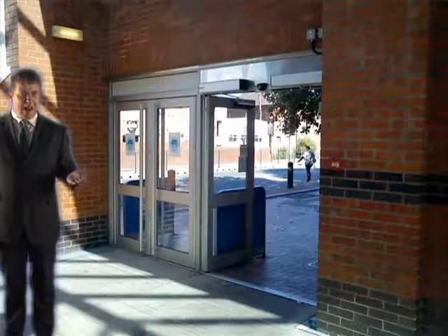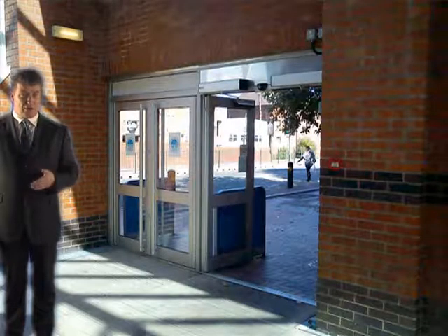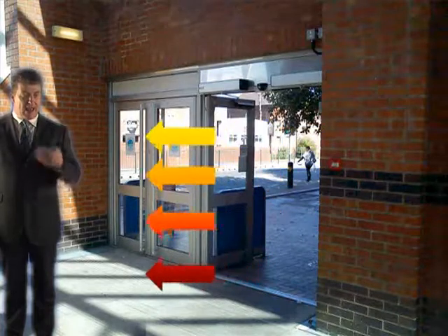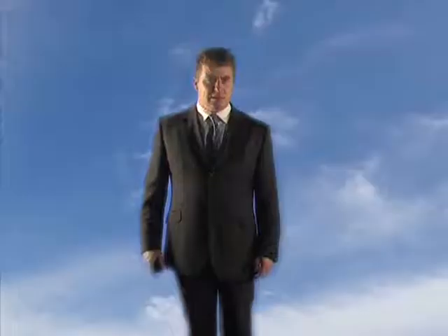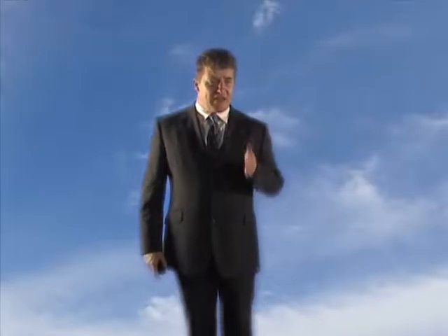The final check that has to be done is to ensure that the replacement air coming in through the exit doors is not so high as to impede escape from the building. Now this is a warehouse, so on the assumption that only staff resort to the building, the maximum velocity that is allowable for the incoming replacement air is 7 metres a second. Now we do not have a figure for the area of the inlet vents that will provide replacement air, so we're going to calculate the minimum required area.